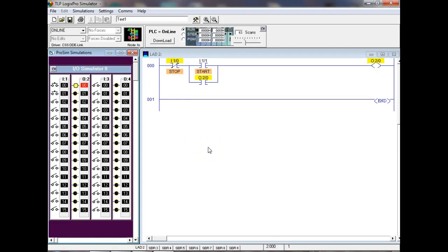But what's the problem? I'm using a normally open button as my stop button. So what would happen if that wire broke coming in on that stop button up there? It'd keep going, because an open wire would be considered an open. Now, if this was motor controls, that would be a normally closed push button. In PLCs, though, we're not going to put an examine if open. We want it to be true when it's what?